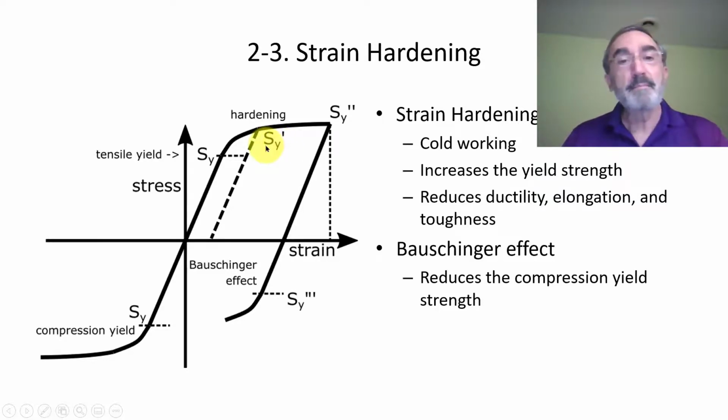Okay, good, great. Now, what are the disadvantages of this? Let's see. The first disadvantage is that now the material works on this dashed line. And if it works on this dashed line, when you go down, you get this permanent deformation. You can never go back there, right? So now your elongation is from here to here, but for the original material, the elongation was from here to here. And the material that has more elongation is more ductile.